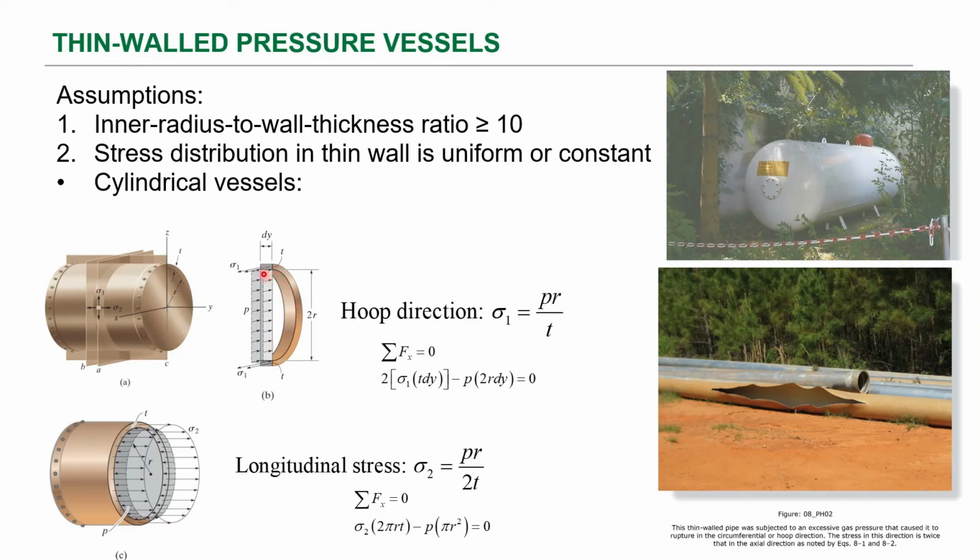So if we take that pressure and say that it's picked up by all of this area here at the top and the bottom, and we do the force balance, we get this expression, which is just that stress times the area, which is that force here at the top and the bottom, minus the pressure that's projected on this area, which is twice the radius,